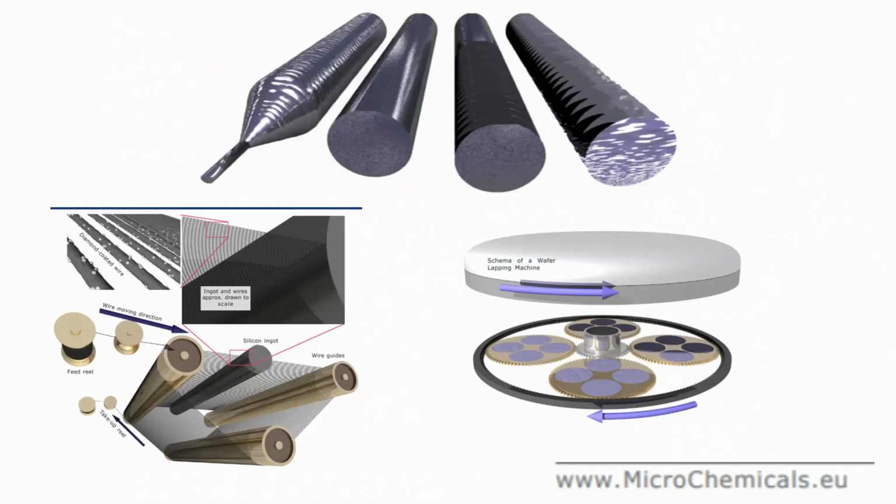Now, this is how it will look like. So, you have these boules, you can see here, this boule, and when you do the edge, you remove the edge by grinding or trimming, then you have this one. And like I said, diamond coated wire is used to slice the wafers from the ingot. After slicing, you can use the lapping machine. You can see here a lapping machine to lap the wafer. After lapping, there is a chemical etch and then polishing, and finally the inspection.